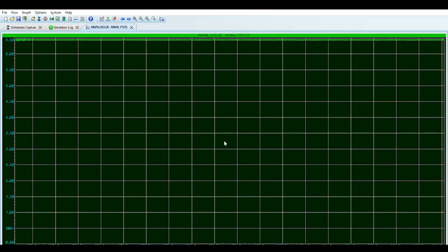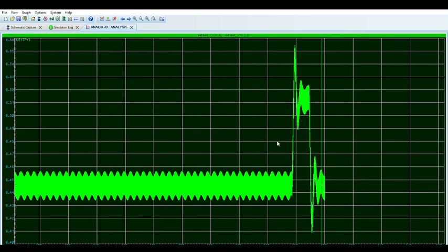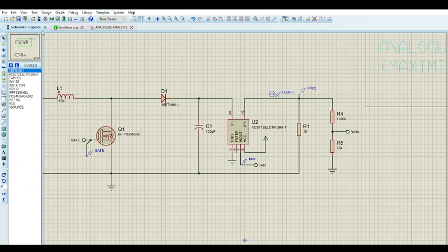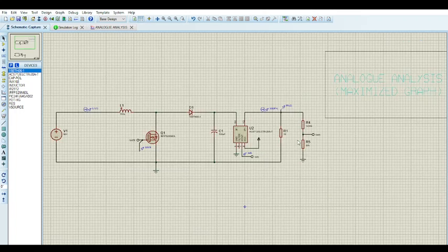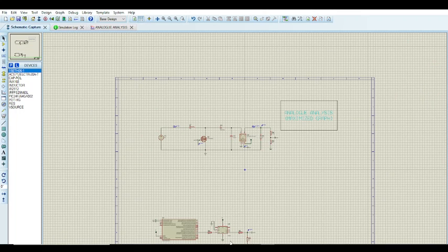And obviously, the ripple that you're seeing here is a consequence of the size of the inductor. But try not to veer too much off of what you calculate. Not too much higher, maybe 2 max, 2.5 max. To be honest, try to keep everything a bit safe, conservative, decent, I guess, and everything connected nicely, soldered properly. Do not spare the solder. And yeah, that's about it.